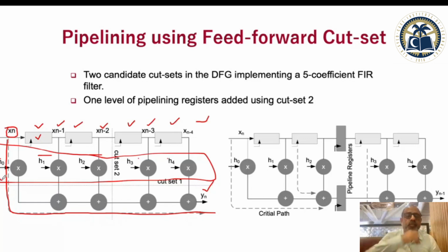but I say I am okay spending area, because usually we have little concern about area because of all the refinement in the technologies, where there are billions and trillions of gates available to you on silicon or even on FPGAs. So the more important concern is the speed at which you can clock your circuit. Now you find that there are so many adders, and an adder is a pretty combinationally complex device. It takes a lot of time for a signal to settle down once it goes past an adder, and a multiplier is even more time consuming.